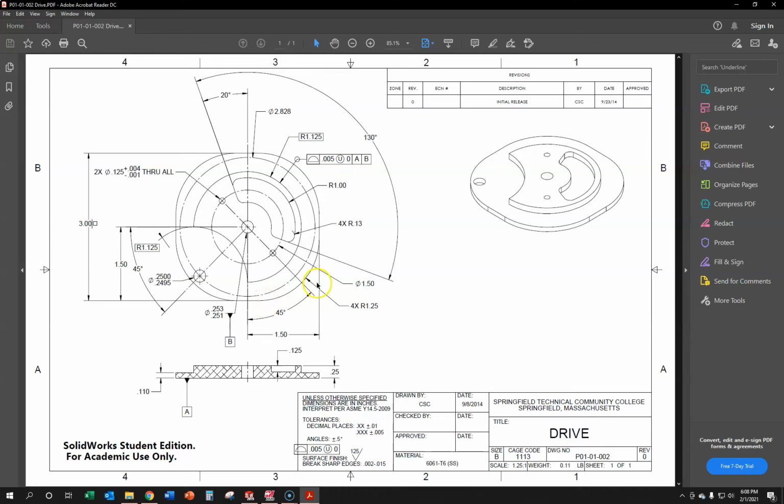But then if you cut it off of a bar in this direction, there's no guarantee that your saw is square or parallel to this surface, so it might be cut at an angle this way, or it could actually be cut depth-wise at an angle. So you'd have to at least face this section here and this here. So what we could do is make a piece of stock that is 3 inches wide, and then go like 3 1/4 or 3 1/2 long, and then machine the 2 edges here. In order to do that, you'd probably have to hang it outside of the vise on one side and then on the opposite side. So that makes the Mastercam setup kind of silly.